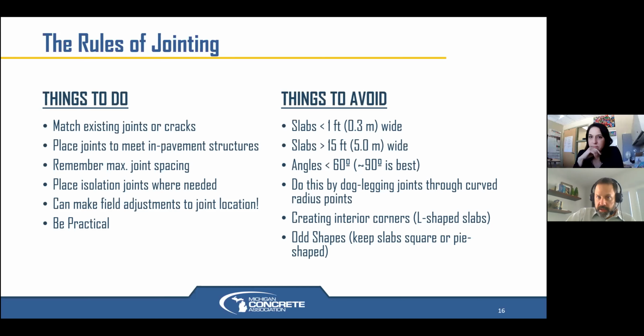Let's run down some of these other questions while we have them here, Heather. Thoughts on the existing asphalt and new concrete interface in a parking lot? Okay, so where we're butting up to existing asphalt with a brand new concrete parking lot, one way or the other, in or out, regardless, it's still best practice to be perpendicular to traffic. Yes.